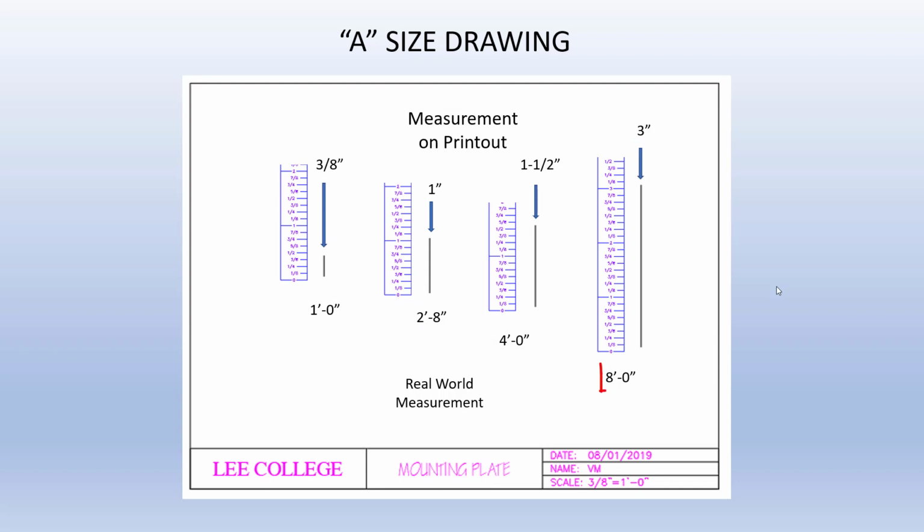Although the concept of scaling may be difficult to understand at first, you will gain a better understanding of the concept with repeated use. One important thing to remember is that you will always draw your object in real-world measurements in model space with very few exceptions.